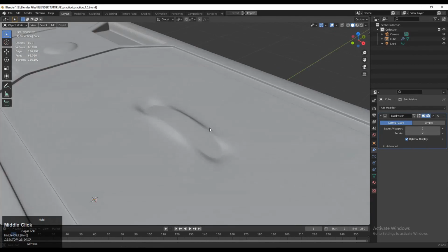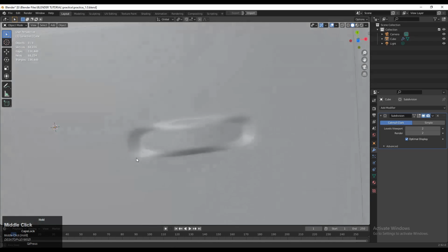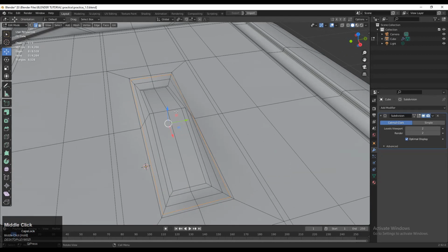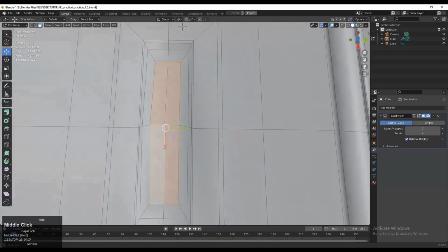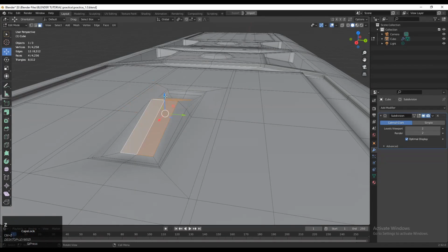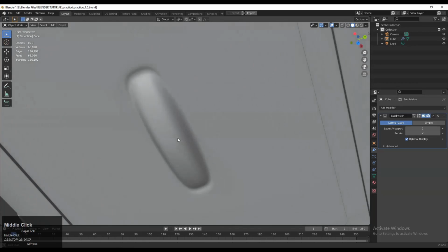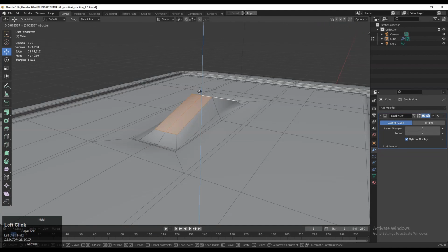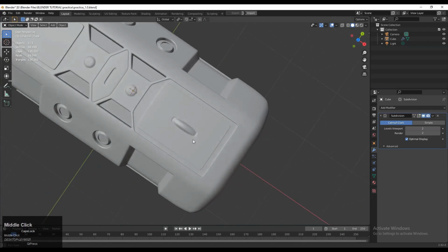If you want to add the insert operation then you can use it, and just add loop cuts, next the loop cuts. Make sure it looks good, so you can see the different design also looks good. By moving these edges also you can create an amazing design. Just increase its height by moving it along the z-axis and we got this decent looking design. Just adjust its height along the z-axis so you will get a decent look for your model.